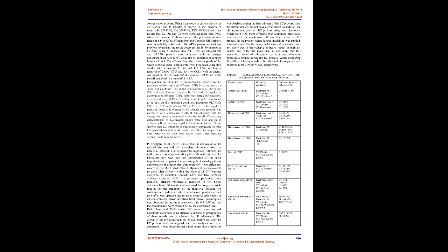The local pH gradients near the electrode surface with hydrocarbonate-free water were previously shown to permit local formation of stable Zn and Fe hydroxides, which actively contribute to their elimination. The presence of hydrocarbonate nearly suppresses this positive phenomenon, leading to far less efficient EC treatment. Whereas removal of zinc cations from carbonated water can be considered as their simple adsorption on the aluminum flocs, Fe2+ ions are oxidized to Fe2O3 by air oxidation after their adsorption. Use of an overall adsorption model allowed quantitative comparison of the EC treatments, with very different adsorption parameters for the 2 metals studied.